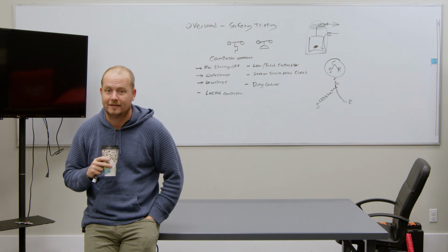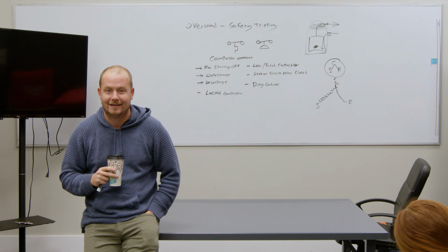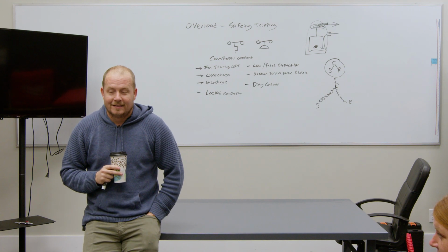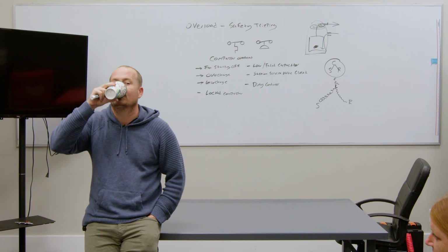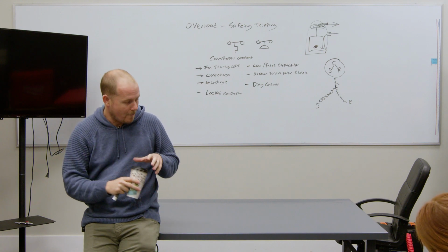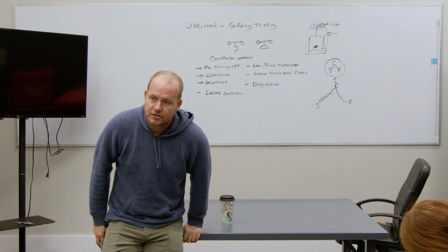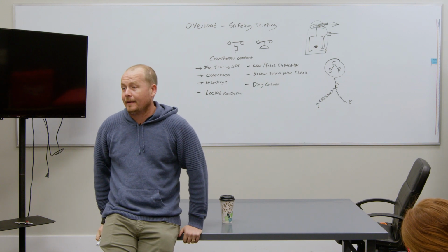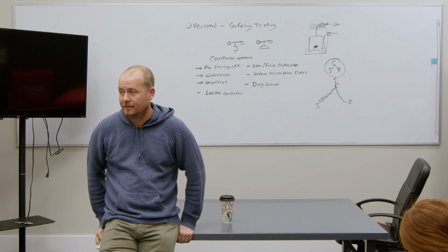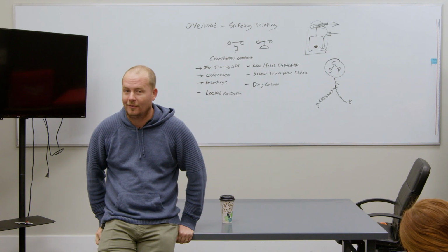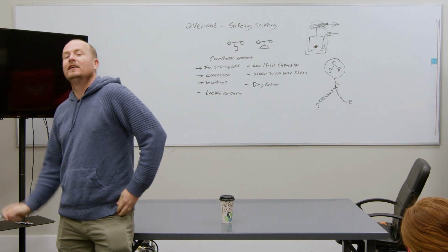You haven't seen it, Jesse? Not completely frozen. I've seen frozen coils, but usually that's due to low charge, with the compressor overheated. Yes, due to low charge. So I'm going to add that I believe that it can happen. I remember it happening when you were training me. All the time. Okay. Every day.